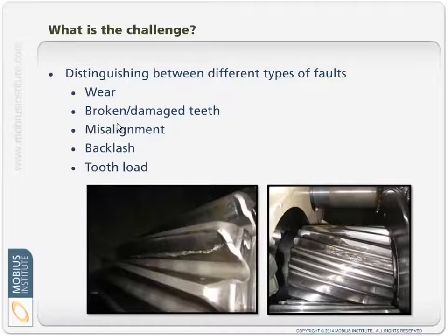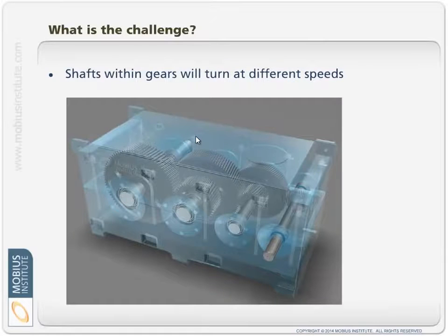We've got time waveform analysis and spectrum analysis at our disposal, and you want to make sure that you use both techniques. That is probably the most important message out of this. You need to do time waveform analysis, and I know I mention it later, but you should also be performing oil analysis to make sure the lubricant itself is good, and wear particle analysis to see if there are any signs of wear. Anyway, let's move along.